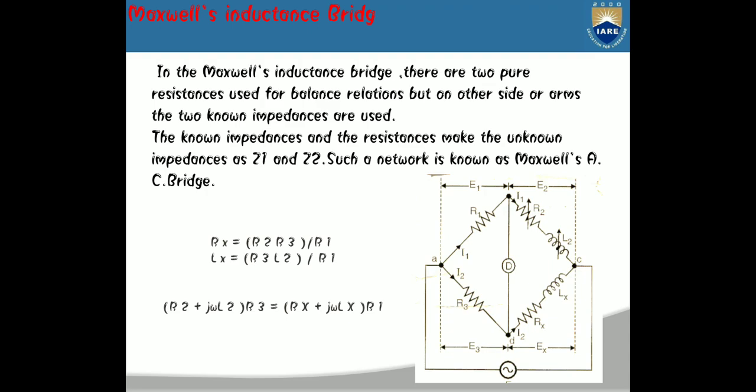It uses the principle that the positive phase angle of an inductive impedance can be compensated by the negative phase angle of a capacitive impedance when put in the opposite arm. When the circuit is at resonance, that is, no potential difference across the detector, an AC voltmeter or ammeter, and hence no current flowing through it, the unknown inductance then becomes known in terms of this capacitance.